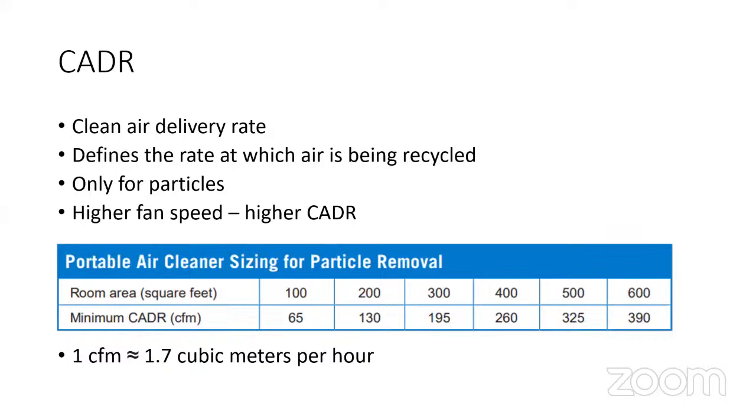So normally when they have specified such room sizes, the height is assumed as 8 feet. So the height of the ceiling also needs to be considered, and the CFM has to be suitably corrected for a higher, taller building.